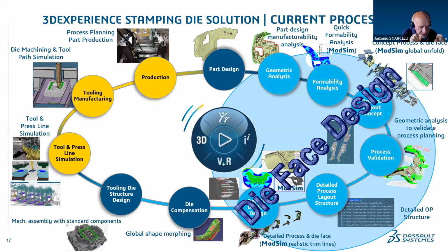And there is a specific wizard. When you launch it, it's very easy. You say, my old part is this one, my new part is this one, and the system will reconnect everything. And it will deliver a table of all the information that it has to check, and it is able to check them automatically. So if all is okay, it will do it automatically and you are safe.